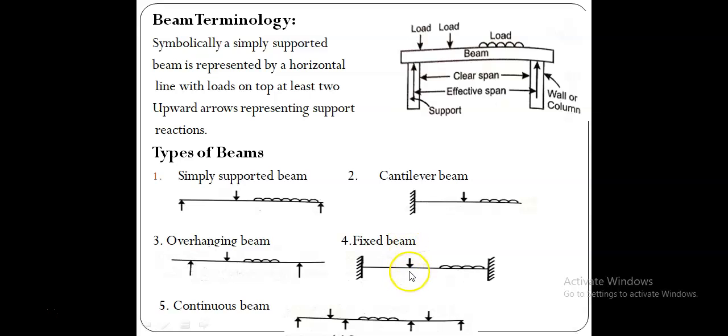In this case, it is carrying only the vertical forces, and therefore we simply neglect the horizontal reactions, because this beam carries only vertical forces and nothing horizontal is produced.